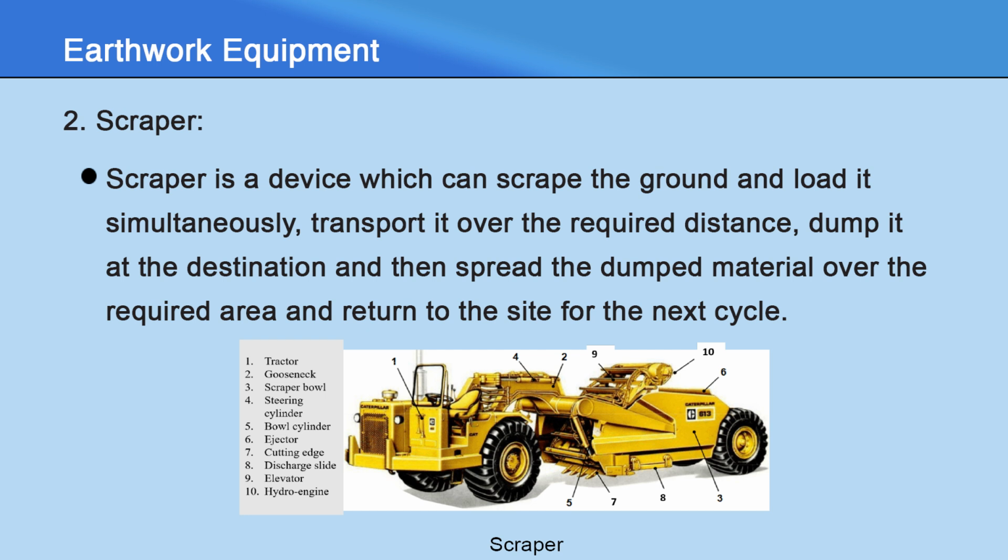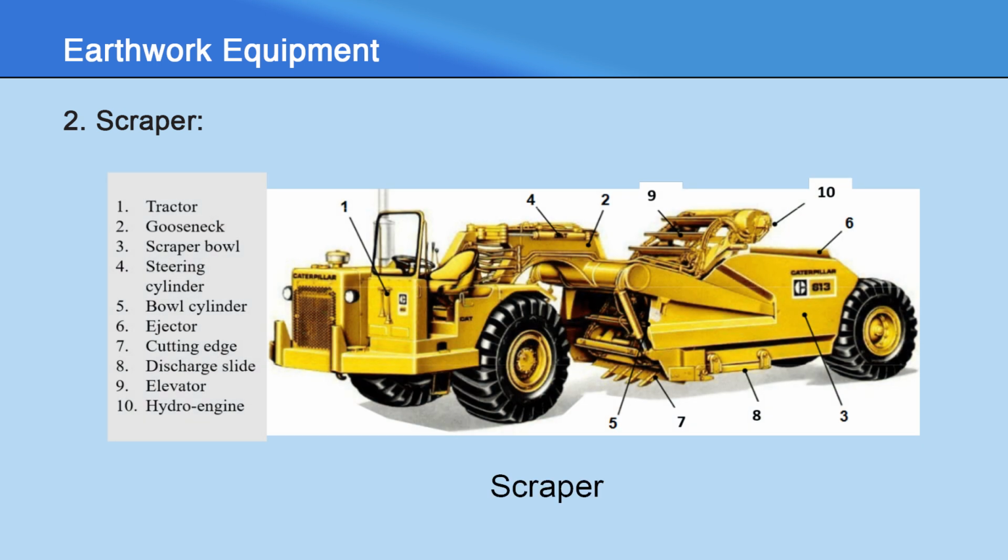They combine the functions of an excavator and a mover. Now, scrapers are not at all suitable to be operated on wet or muddy materials or hard rocks. They are used for leveling, loading, hauling over distance varying between 150 to 900 meters. Scrapers are generally pulled by a tractor and are self-operating in that they can load, haul and discharge the materials.